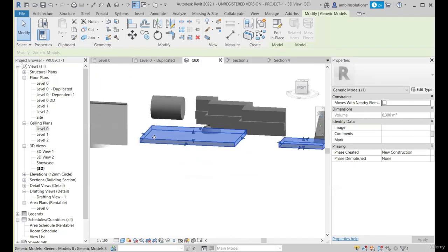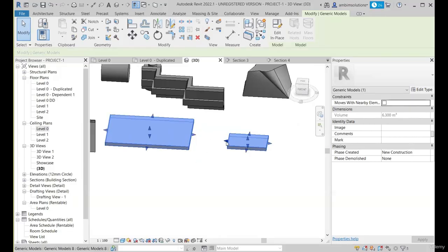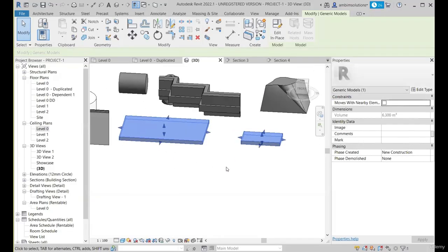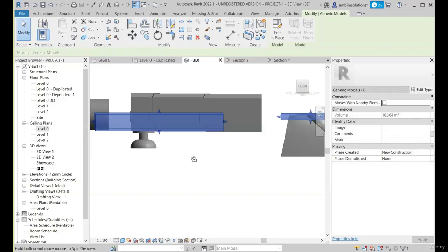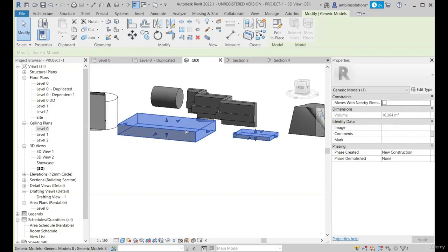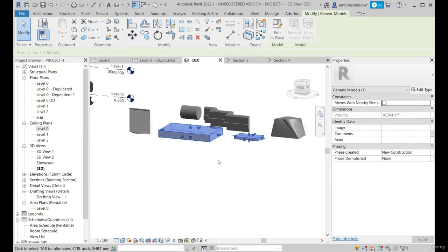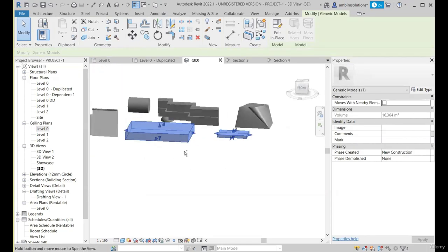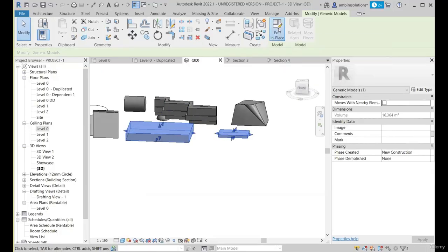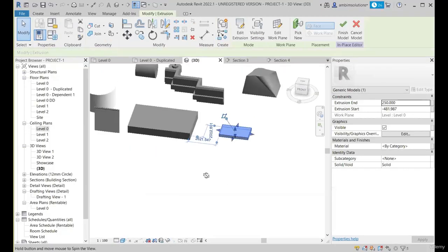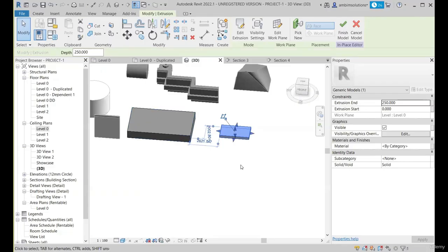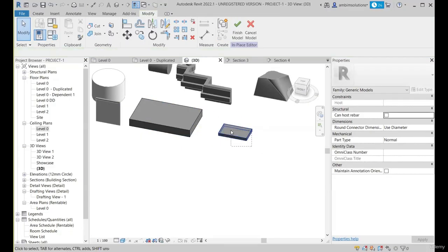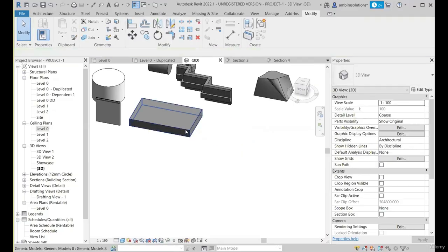This is because we have created another extrusion without finishing the modeling part of the extrusion that we created first. So whenever I select any of the boxes or any of the extrusions, both elements will be selected at once, because this is also part of this model in place rather. Whenever you go to edit in place, you can see we are able to change both. This is because they are interrelated. So if you delete it and finish, we have only a single extrusion here.